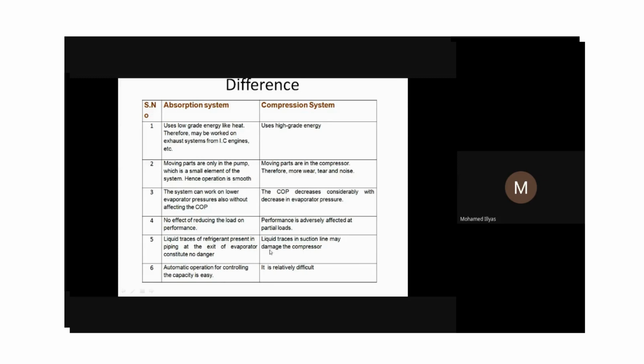There is another terminology we call the relative COP, which is nothing but comparing our actual and theoretical COP. What is actual and theoretical COP? The theoretical COP means by design calculation and analysis, we get some COP value. The refrigerant leaving the evaporator and entering the compressor should enter either in the dry saturated state or superheated state. So we'll get some COP value.